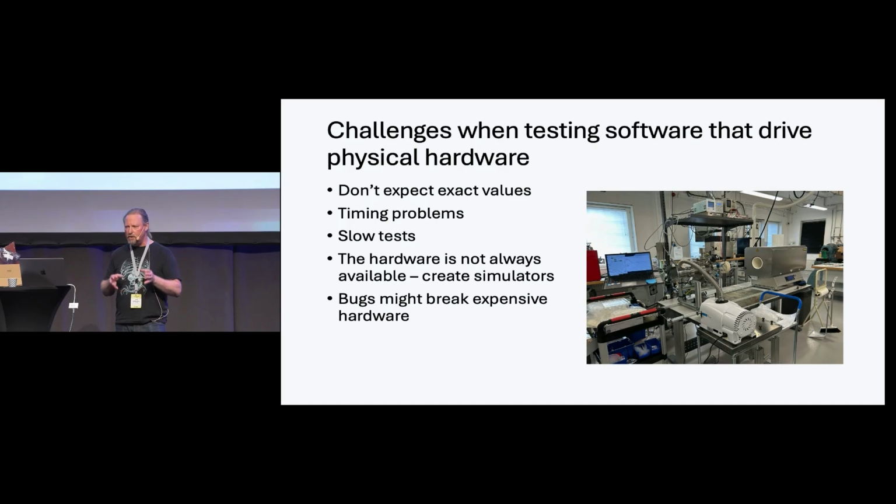You still should do a lot of testing, but don't expect to get the same result every time you read a sensor. You might expect it to give the result 5 volts every time, but it will sometimes be 4.999995. Next time 5 point something. It will differ. You will have noise.